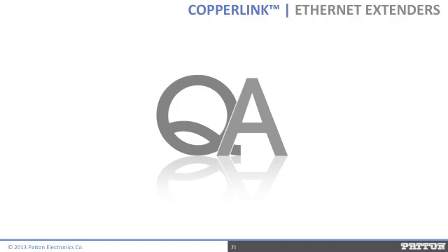Thanks, Johnny. Nathan, back to you. Is MDE a field bus technology? Very good question. No, it is not a field bus technology. Rather, it is an Ethernet extension technology with additional capabilities. With Ethernet extension, you connect to any standard copper version of Ethernet in order to go beyond the 100-meter maximum segment distance.